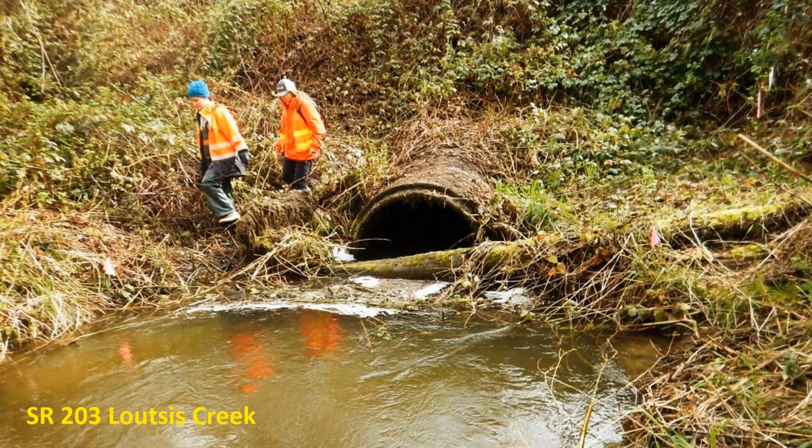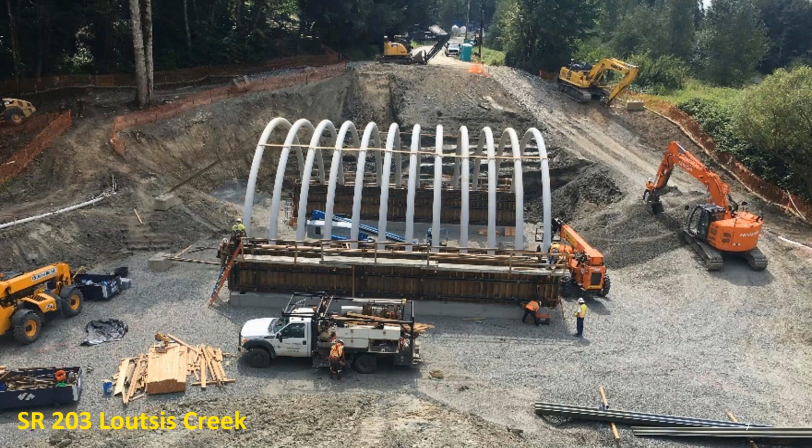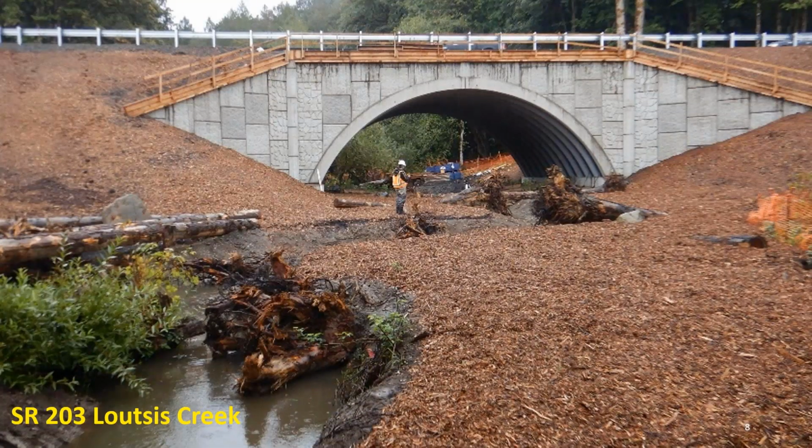So I'm going to go through 3 really quick examples here before I turn things over to Bijan, just to show you the sort of projects that we're addressing here. This happens to be SR 203 Louses Creek, and you can see that is the current fish passage, and fish just don't make it up there. It's too high velocity and it's too congested. So this was addressed using a composite arch bridge, which is 1-foot diameter composite arches, which are filled with cement grout. And then you put a composite decking on top of that, and you backfill it with earth and structure earth walls. And here's a picture of the completed project.